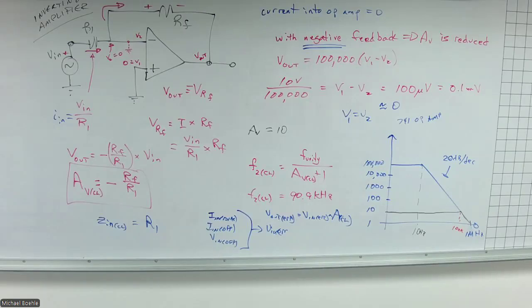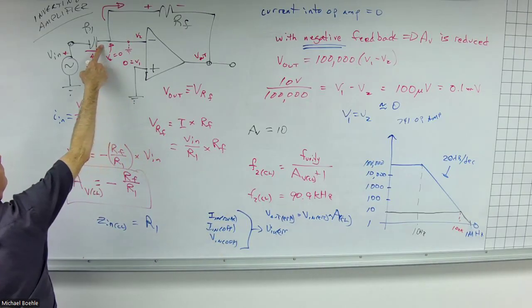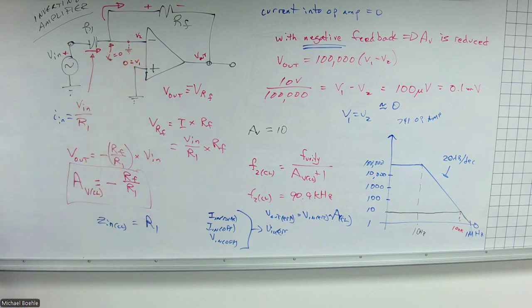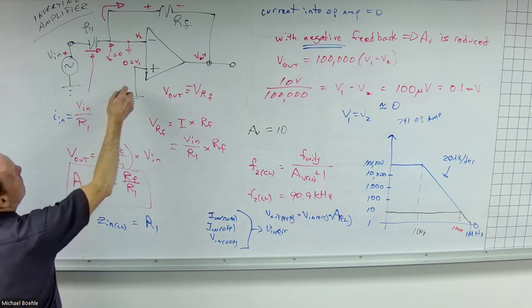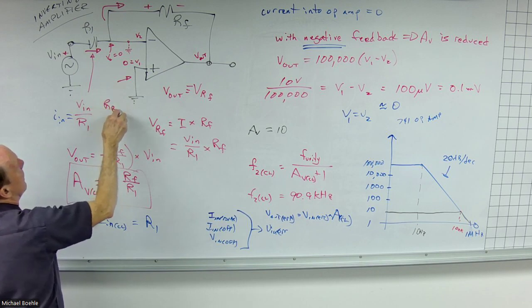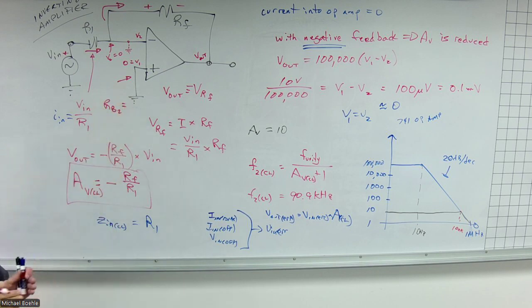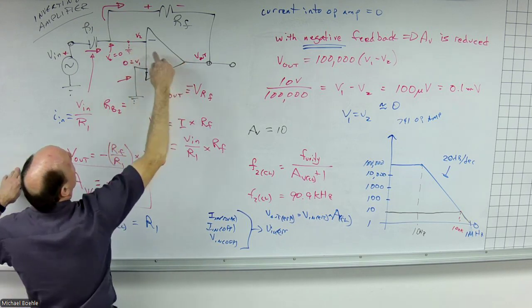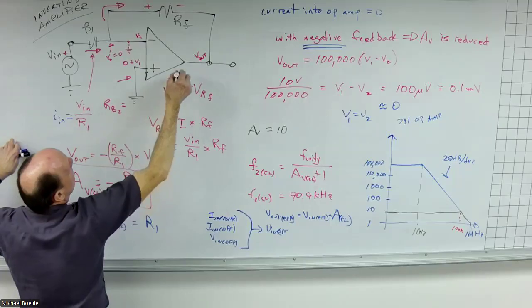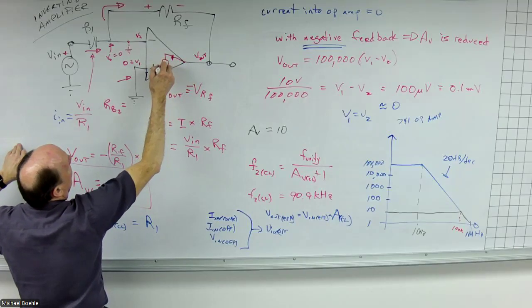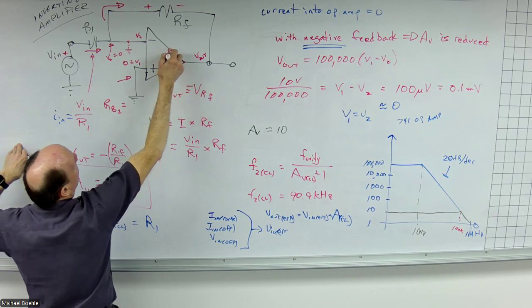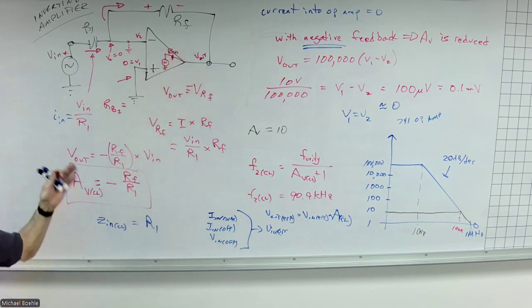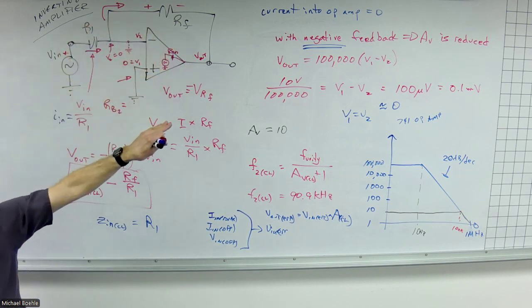Now, I do only have resistors on one input. So what would I want for a matching base resistor down here? Keep in mind that we're looking at 2 different paths of current here that does actually allow whatever current goes in there. So inside here, we have that output resistance. This output resistance is relatively small compared to these other resistors.